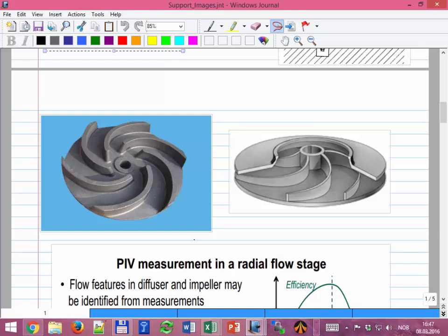If you remove that cover up here, you will see exactly that. Okay, so it's rotating, the fluid is coming in the inner part and then it's exiting through the outer part. And that's what's giving this change. When the fluid enters into the middle part, it has some velocity that is given by the rotational velocity of the disk. When it's exiting in the outer part, it has a different velocity, which is higher. And this difference in velocities between this inner diameter and this outer diameter is what causes the pressure increase.